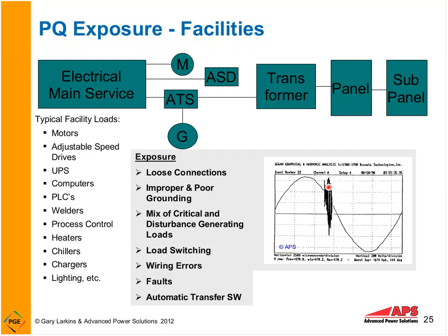The biomeds had just a stack of boards that they kept fixing and replacing. Of course, this was not a good thing when it caused the surgery suites to go up to 90 degrees right in the middle of surgery. The solution for that was proper surge suppression and filtering, and also replace the contactor with one that wasn't as pitted. Newer contactor also helped with that.